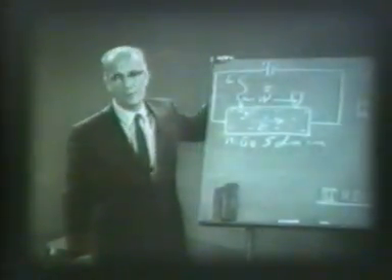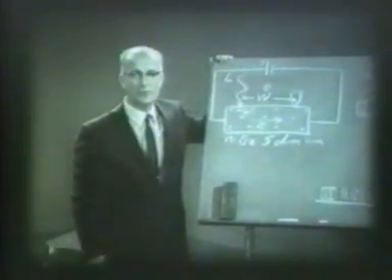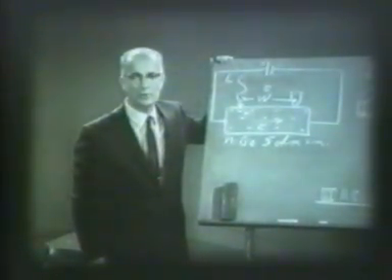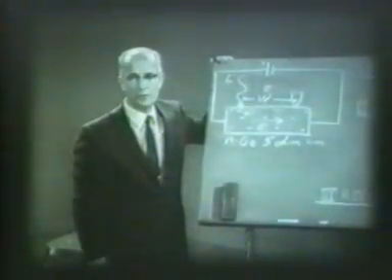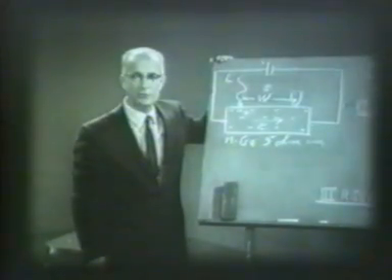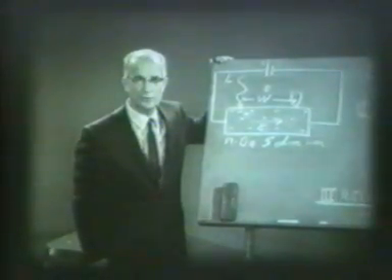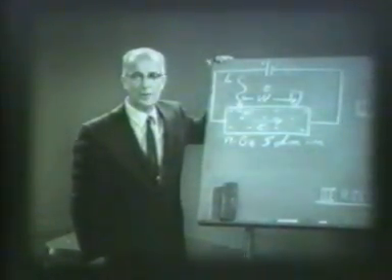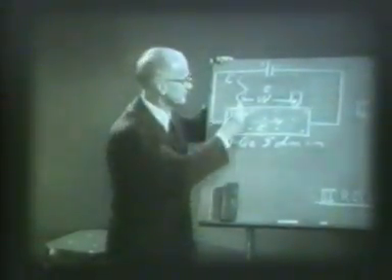Before our experiments, drift velocity was not measured directly, but instead inferred from conductivity and Hall effect. Furthermore, conductivity and Hall effect are concerned chiefly with majority carriers and give little or no information about minority carriers. In contrast, our experiments focus attention on the motion of a pulse of minority holes.